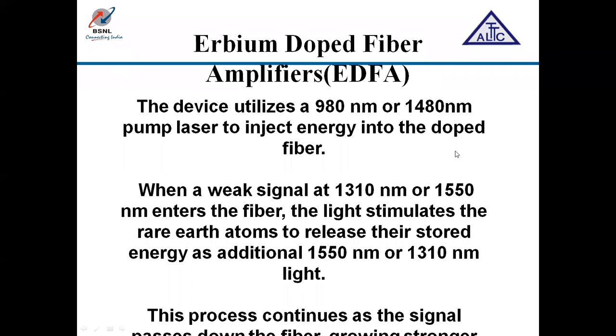This device, EDFA, uses a 980 nanometer or 1480 nanometer pumping laser. You should remember here, EDFA uses 980 nanometer or 1480 nanometer. Each signal, 1310 or 1550 nanometer, whatever the signal is, gets their stored energy added as additional energy on that line. The process continues as the signal passes down the fiber, acting like a repeater.